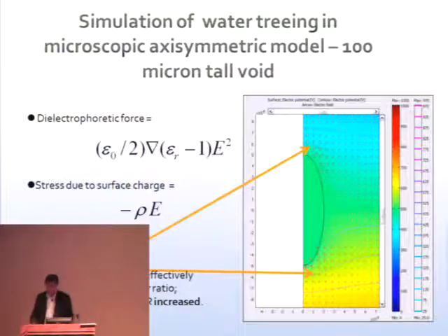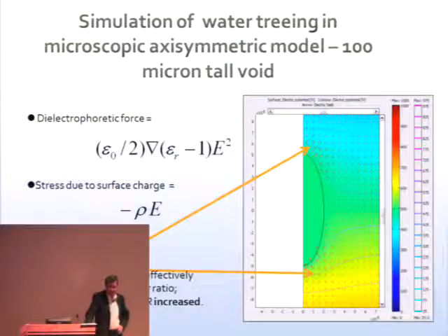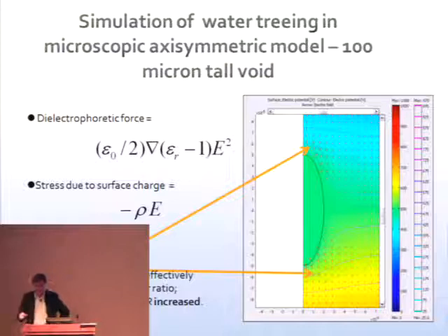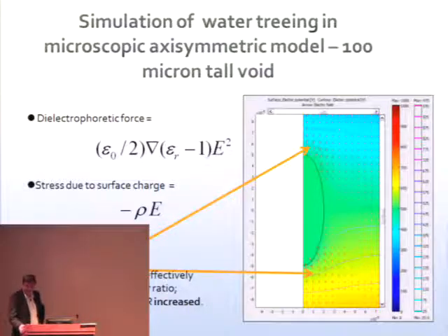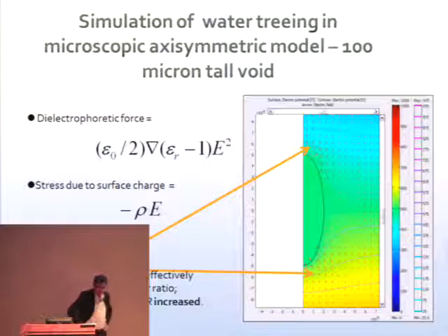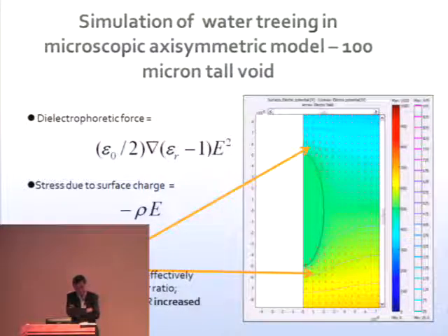Okay. Just one comment about the temperature. It's not, in my experience... I mean, the worst performers in this kind of water tree environment are cables that are barely loaded or even not loaded at all because they're energized from just one side. Yeah, but how do you know what happened 20 years ago? No, these cables are tap lines. They have a few transformers that can't be overloaded. There are a lot of other cables, main feeder lines, where we don't experience cable failures, more accessory failures from connections and the like.